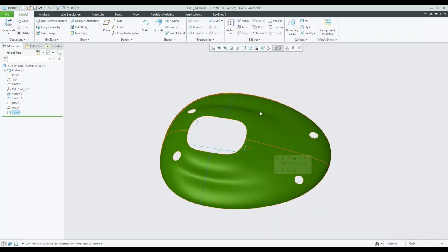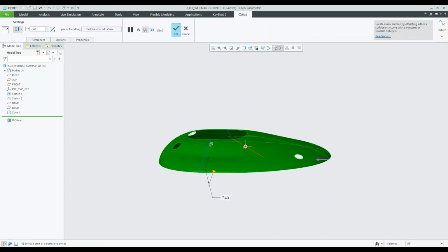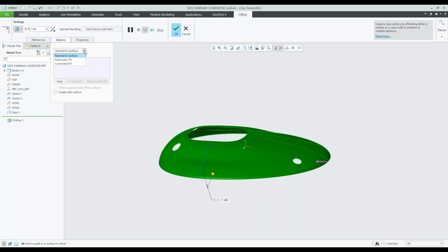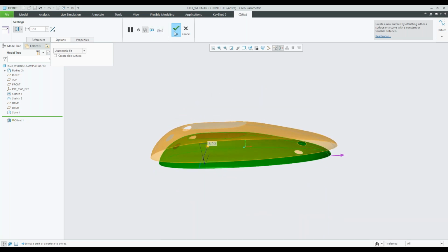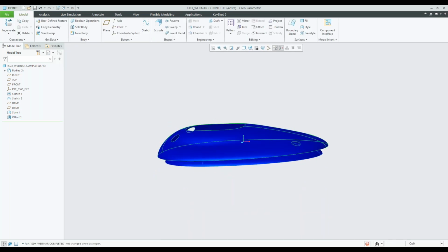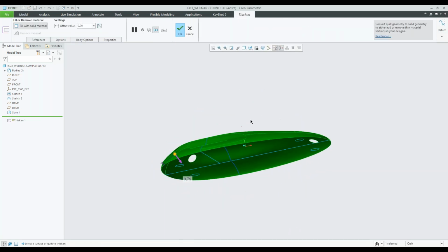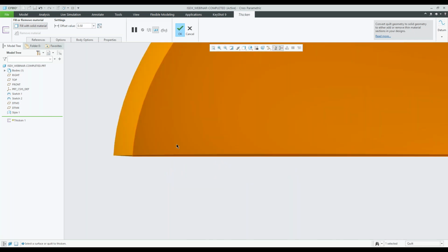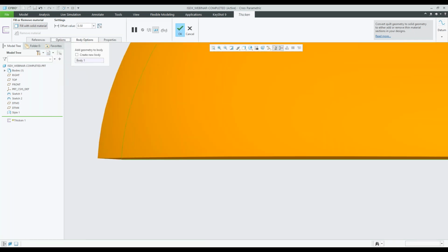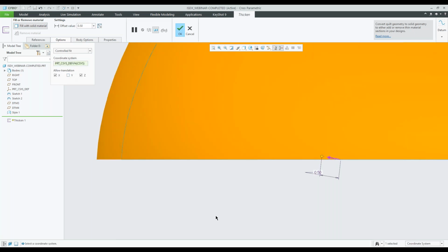And then if I change this to quilt, I can grab that surface, I can offset it a little bit, change that there. There's automatic, right? Let's undo that. We can actually select that as well and do thicken, all right, and thicken that surface, right? Let's go to the front view here. And let's turn off controlled fit and turn off the Y direction, all right?